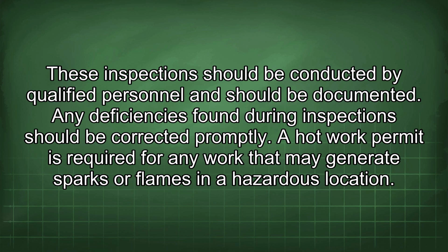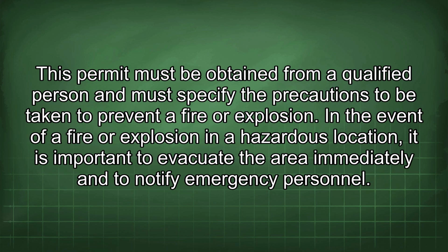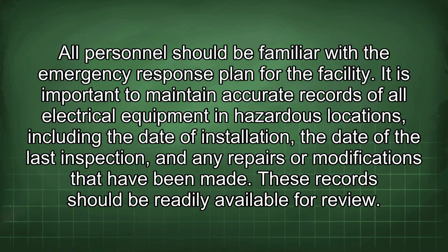A hot work permit is required for any work that may generate sparks or flames in a hazardous location. This permit must be obtained from a qualified person and must specify the precautions to be taken to prevent a fire or explosion. In the event of a fire or explosion in a hazardous location, it is important to evacuate the area immediately and to notify emergency personnel. All personnel should be familiar with the emergency response plan for the facility.